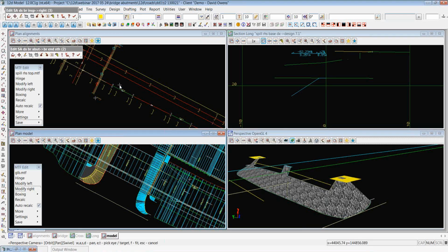What's the best way you recommend for showing retaining wall top and bottom and footing steps? So in terms of the actual long sections themselves, I guess is what he's meaning. Putting them on a plan, documenting, that's a bit of a tricky one. Essentially, they are just super alignments, one for the base and one for the top. So we can plot those strings together onto just a normal long section plot, and that's going to have all the levels and links of the different segments come out of it automatically.